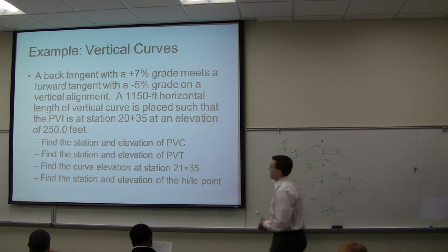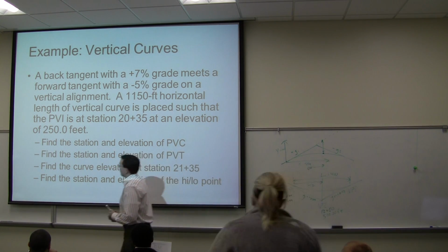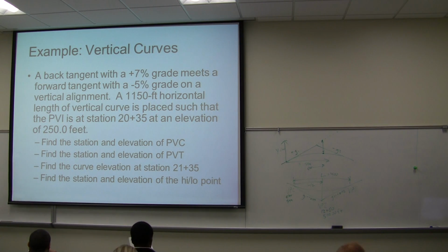All right, so let's look at an example. We have a back tangent. So what's back tangent mean? If you're starting at the VPI, looking back to the VPC, that would be your back tangent. So it has a plus 7% grade, and it meets a forward tangent with a negative 5% grade. So is this a crest curve or a...